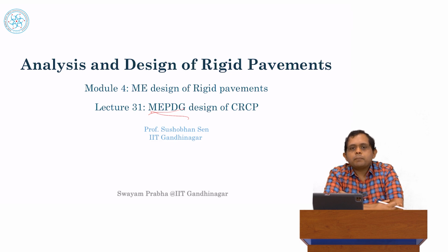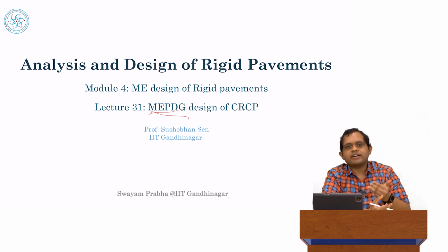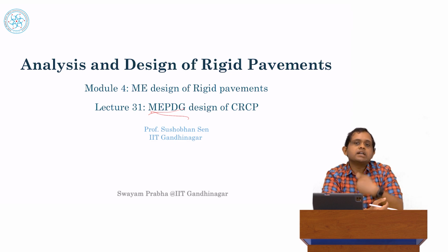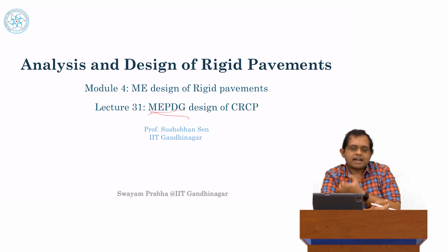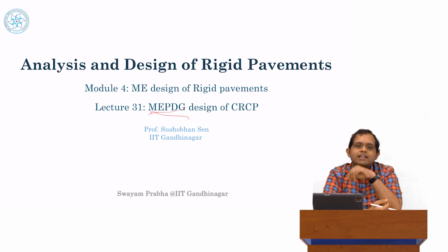Okay, now based on that, in the previous lecture, I showed you how we combined all this knowledge. So all this knowledge of analysis, finite element analysis, all this knowledge of transfer functions and fatigue damage, etc. All of these topics which we've been learning over time. In the previous lecture, we actually brought all of it together, and I showed you how MEPDG calculates or designs JPCP.